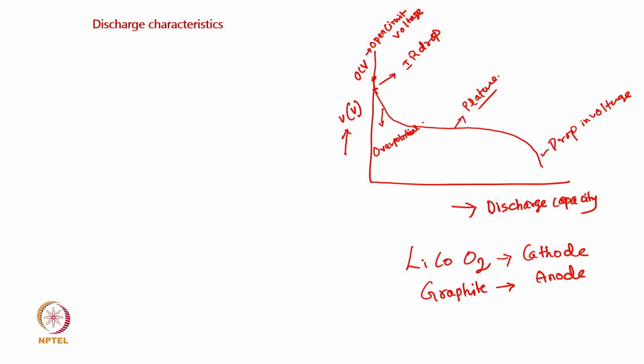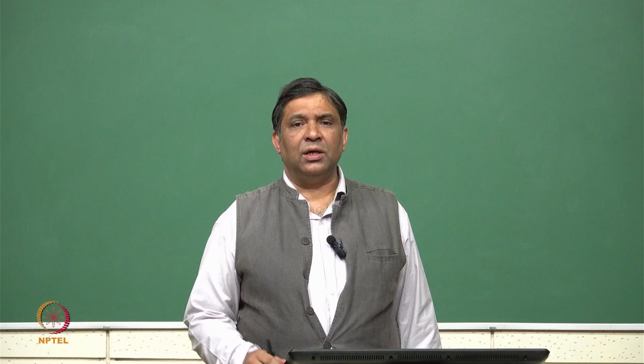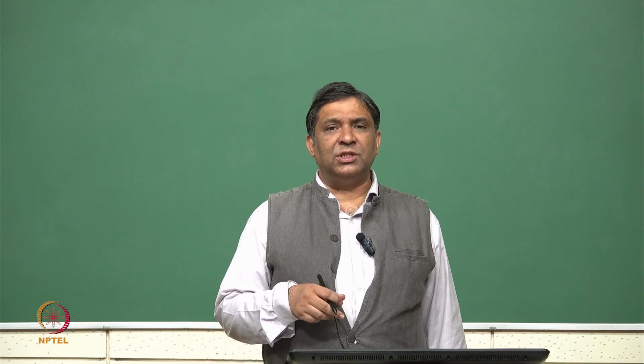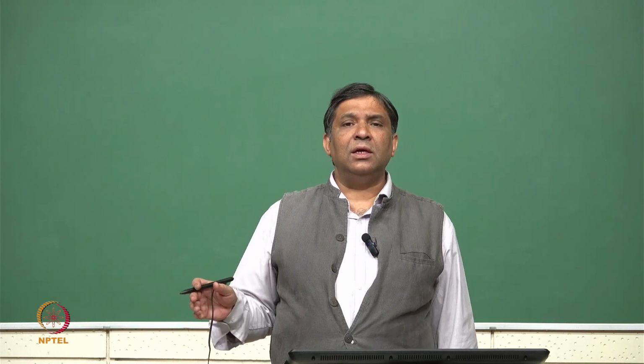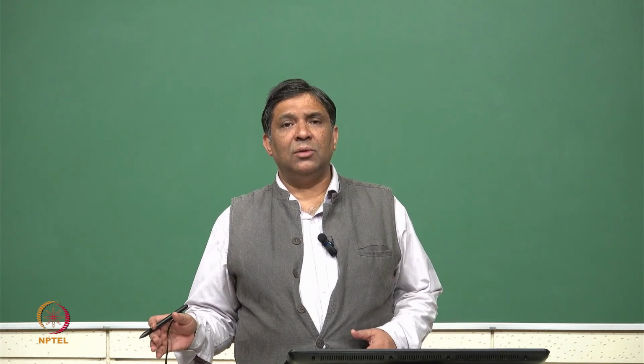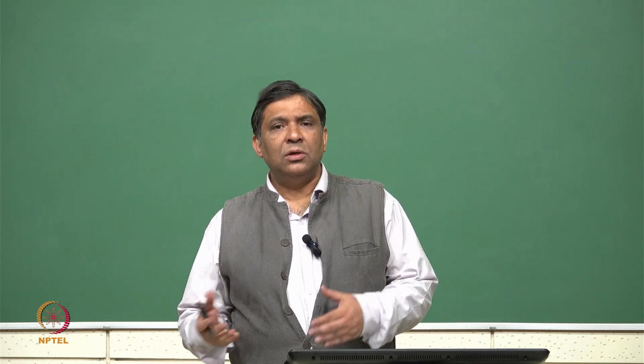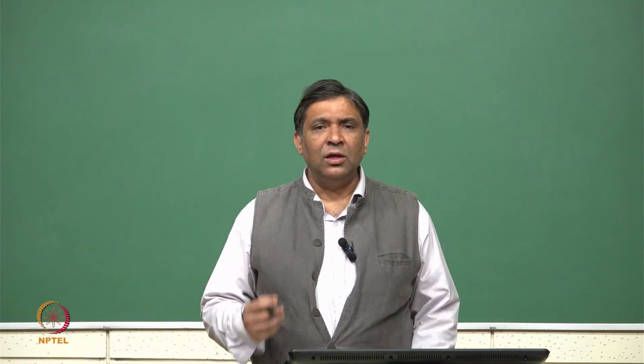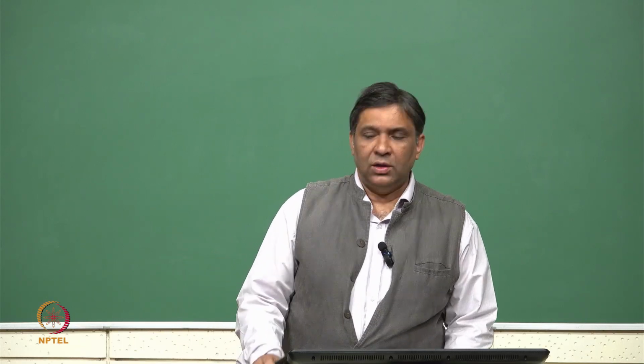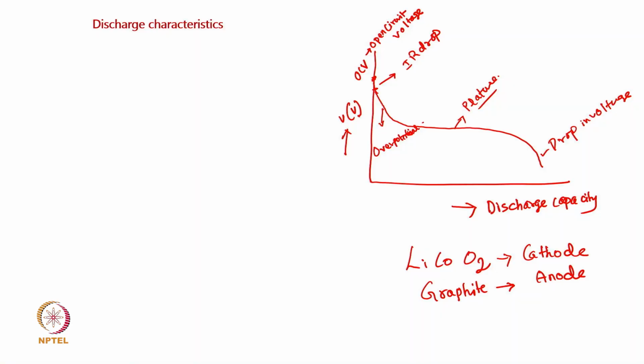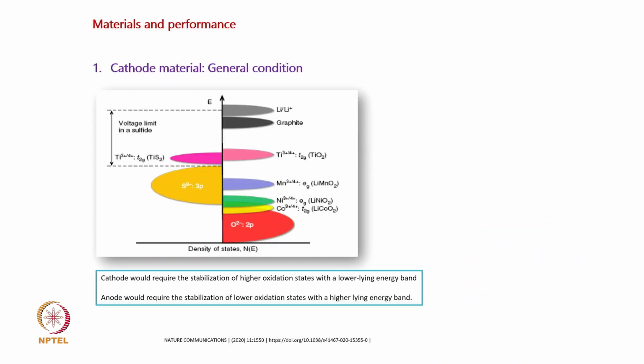Okay. So, now again, if you have to charge, then plug it into a socket, and again the process starts. Okay. So, again the anode gets lithium ion from the cathode by the intercalation process, and the cycle continues. All right. So, this is the way a lithium ion battery works, its charging cycle, discharging cycle, and the voltage and discharging capacity characteristics. Okay.